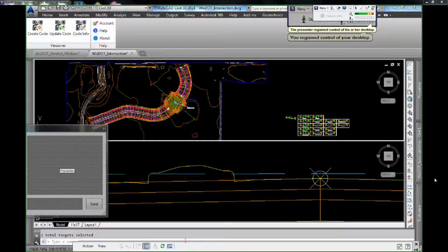Now, at the time, I thought we had tried the Autodesk version of subassemblies and had the same problems, but that was 4 years ago. I don't remember for sure anymore. But we steered away from the offset assembly usage for that reason, because our corridor surfaces need to be feature line based, and the feature line definitions weren't carrying into the corridor surfaces in the areas where we were using offset assemblies. Okay, that might explain that issue I had there on that left turn lane.